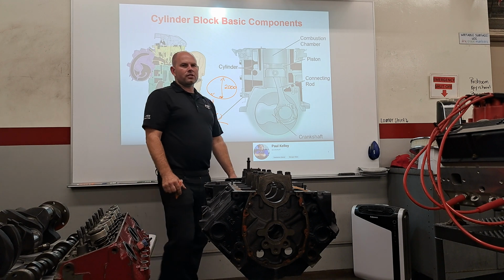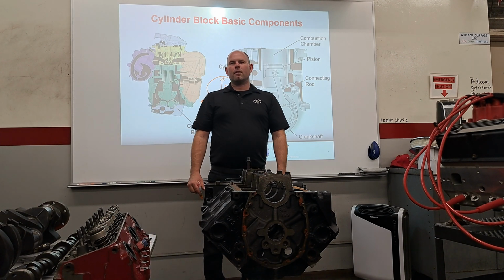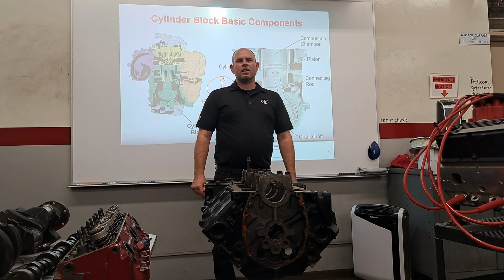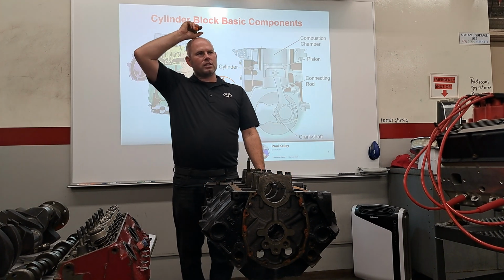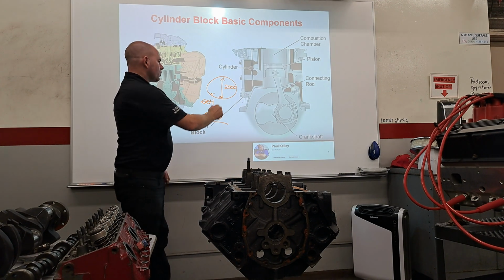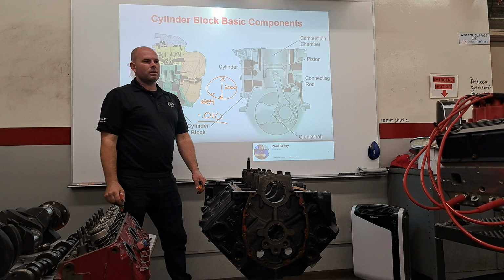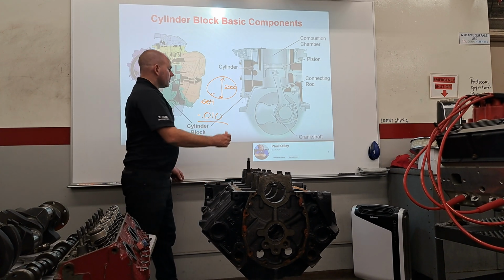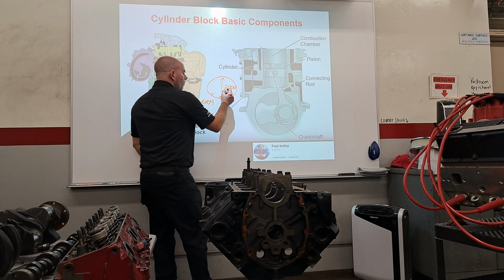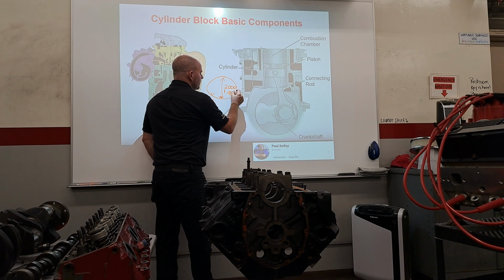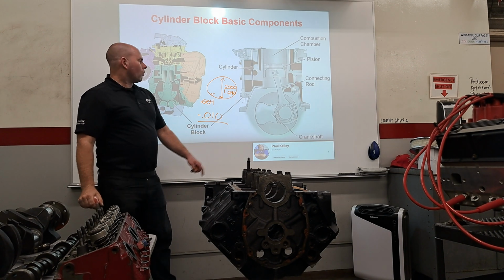Because you don't just set the machine. You're cutting it. You're machining it. How do I know when I've got to the 10 thousandths number? Can't you measure it? Yeah, exactly. So if it was 2.000, what should it be when I'm done? 1.990. There we go. 1.990 would be 10 thousandths less than 2.000.